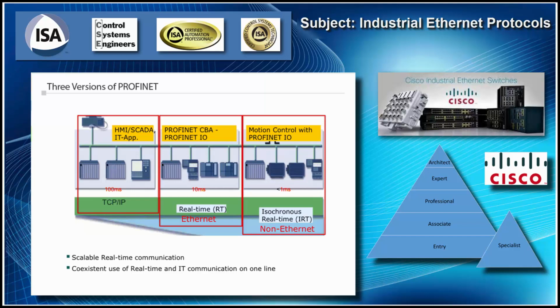requirements. PROFINET Isochronous Real-Time, or IRT. At this level, signal prioritization and scheduled switching deliver high-precision synchronization for applications such as motion control. Cycle rates in the sub-millisecond range are possible with jitter in the sub-microsecond range. This service requires hardware support in the form of readily available ASICs. In each of these implementations, PROFINET protocol does some portion of the OSI model function.